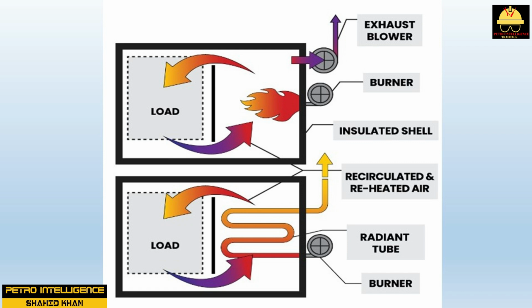Fire tube heaters are indirect-fired. They contain the combustion gases in tubes that occupy a small percentage of the overall volume of the heater. The heated tubes run through a shell that contains the heated medium. A fire tube heater resembles a multi-pass, shell-and-tube heat exchanger.